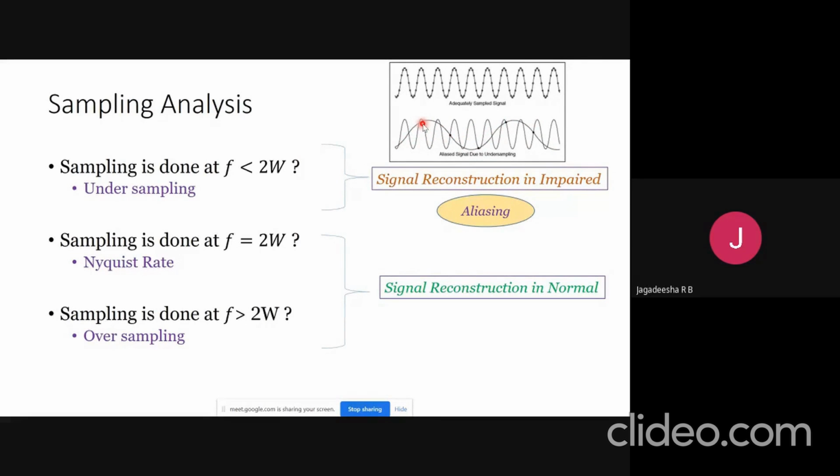We are not exactly representing where the original frequency's amplitude or time was. This is called aliasing. So these low frequencies are occupying this place instead of occupying the original positions or somewhere very near to the original position. This process will inhibit us from reproducing the original signal. So this is the aliasing effect.